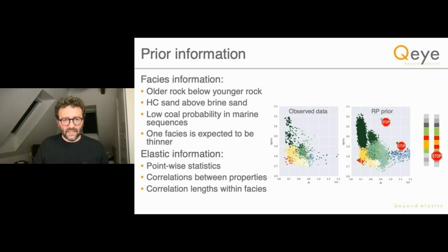So the idea, at a very high level, is to infuse broad prior information, with emphasis on broad, and then add the strong constraints of all the stuff we are absolutely sure of directly into the inversion. And by reducing the solution space dramatically, the solution buried or hidden in the noisy seismic data should pop out at us. That's the hope. But it's important to stress that we want the data to speak, so it doesn't become a modeling exercise.